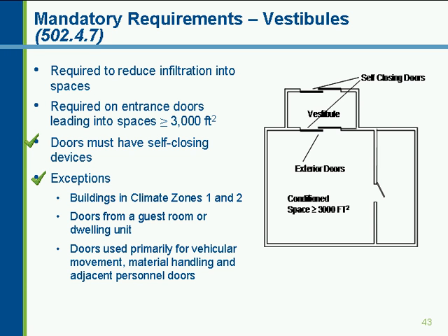Also, the one bullet I don't have on here are revolving doors. If I have a revolving door, for example, in a lobby of a hotel motel, you would not have to have a vestibule on that particular door. So there are some exemptions on the vestibules that are in the IECC right now.